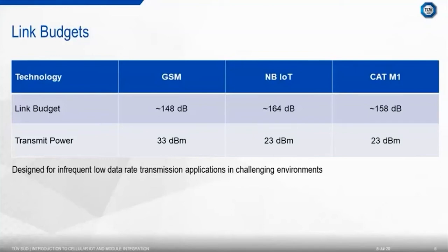The link budget is impacted by factors including transmit power, antenna gain, receiver sensitivity, frequency, path loss, modulation scheme, and signal-to-noise ratio on both sides of the link, relating to both the base station and user equipment. From the figures shown in the table, it can be seen that Cat-M1 and NB-IoT offer improvements over current GSM technologies at a reduced power level. The reduction in power is an important factor, as well as simplified signaling processes and power-saving features, to achieve one of the key goals of the technology, long battery life.